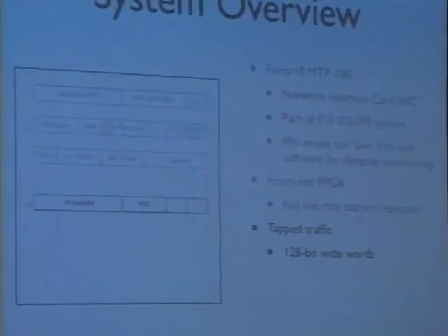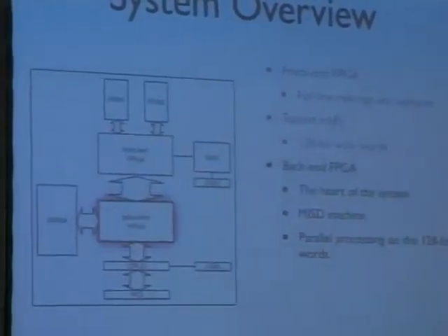Then it is followed by the destination MAC, and then you have a little bit of room left, 16 bits, and that's where the source address starts. Once this is on the bus, there is a second word which contains the rest of your data, the rest of the 128 bits, and a third word, and it goes on until you reach the end of the frame. And then you get the next frame. And that ends up at the backend FPGA.